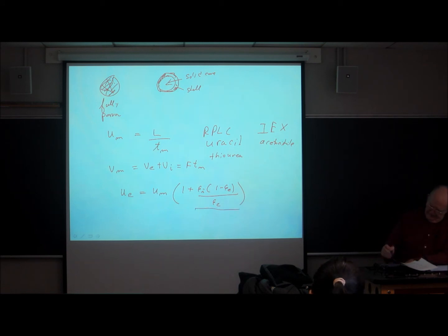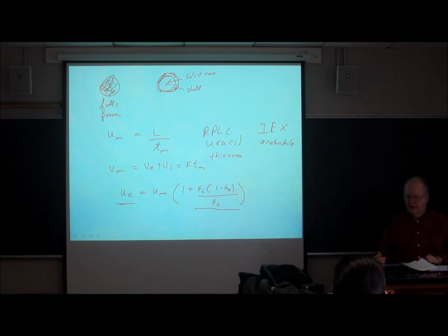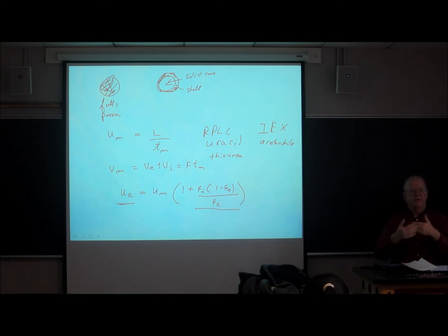Since this is a positive number and we're adding it to 1, the interstitial velocity is greater than the zone velocity. The zone velocity includes the fact that molecules fit inside the particles. The interstitial velocity says all we care about is the velocity when they're outside the particles. So this has got to be higher than that with a given flow rate.